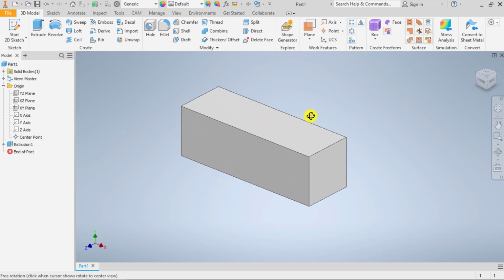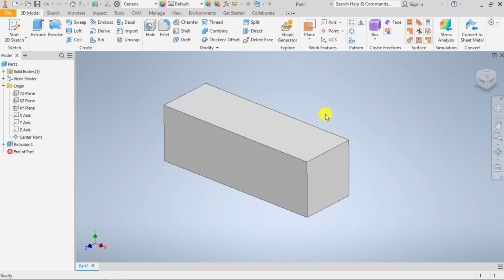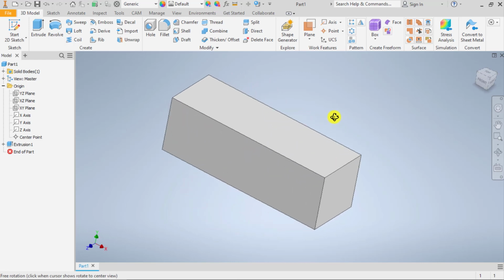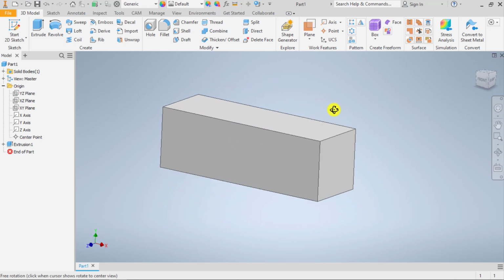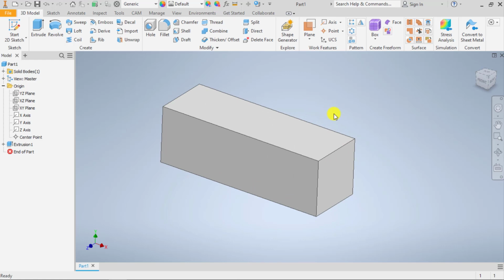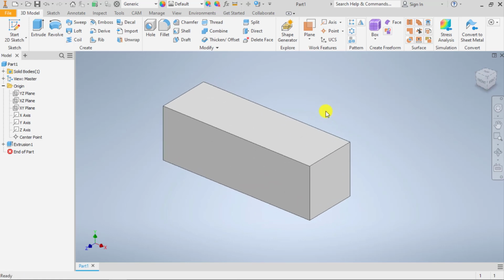The way that I'm doing that is holding down the Shift button on the keyboard and at the same time clicking in on my mouse wheel, not scrolling, but clicking it in and holding it. And now I get my orbit. I prefer it that way. It's easier. There's no steps. I can just click. I usually keep my left thumb over the Shift button anyways. Inventor is not as keyboard intensive as AutoCAD can be should you choose to be a keyboard person on AutoCAD.